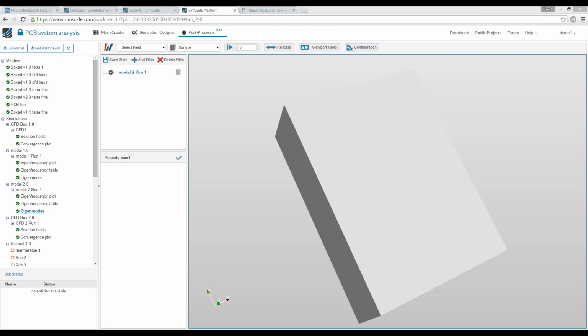All right, another question. Do we have the possibility of repairing the geometry? For example, gaps between the edges. At the moment, we at SimScale are focusing on the thing that we know best, that is simulations, and we leave CAD to great partners such as Onshape. So we do not provide automatic CAD repairs. At the same time, depending on the quality of the CAD or the size of the gap, it might happen that the mesher itself will completely ignore it. So you could consider this a part of the repair. Still, I highly encourage people to go and repair the CAD online, since it's just a click with a mouse.